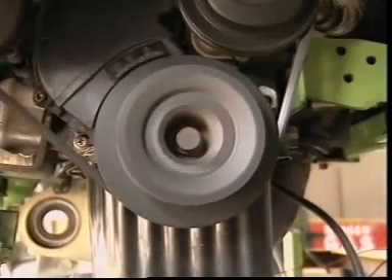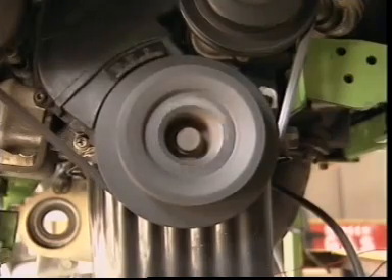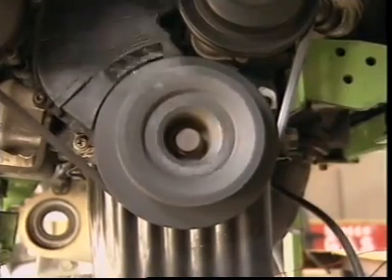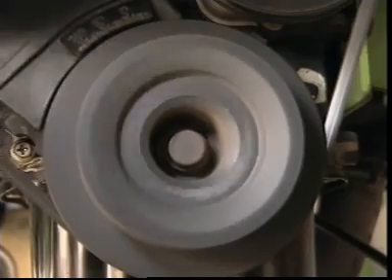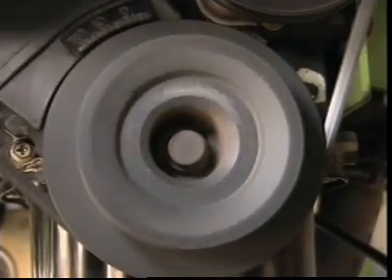If the control unit is programmed to maintain a fine control of the idling speed, perhaps to within 100 RPM, ignition timing can be used. Advancing the ignition point increases engine speed, just as retarding it decreases it.